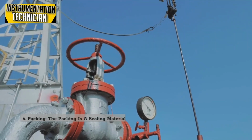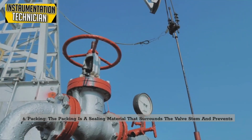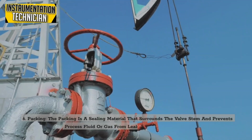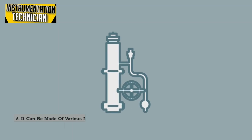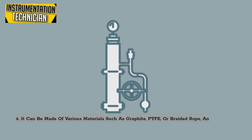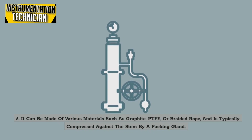6. Packing. The packing is a sealing material that surrounds the valve stem and prevents process fluid or gas from leaking out of the valve. It can be made of various materials such as graphite, PTFE, or braided rope, and is typically compressed against the stem by a packing gland.